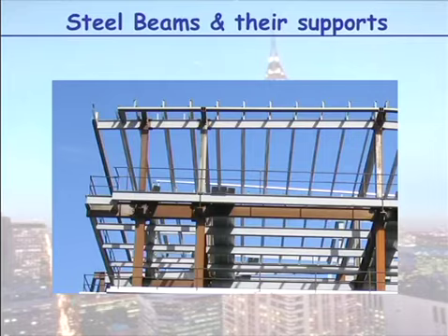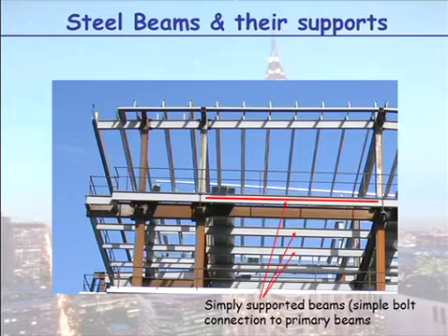Here in reality, let's see what we can find in this bit of building here from Chatswood that I illegally photographed, because you need a license permit to photograph anything there. Okay, so what we're looking at here is these members through here. They're all simply supported beams. I know it's very small in here, but you can see there's only 1, 2, 3, 4 bolts supporting the beam to these very deep universal beams. So there are simply supported beams.